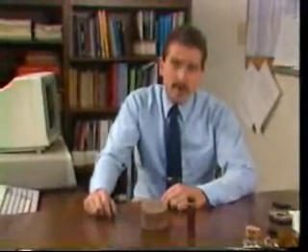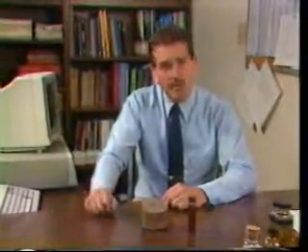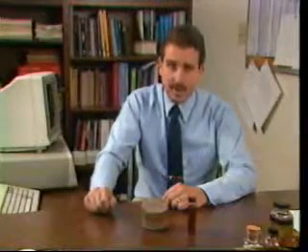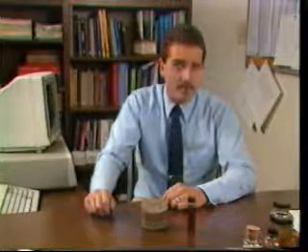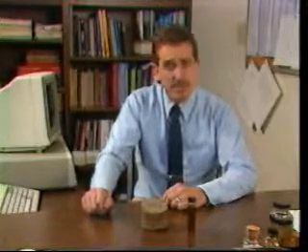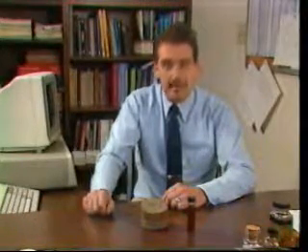Let's summarize the material covered so far. In the first unit, we mentioned the basis for well test analysis and interpretation. We spoke of three necessary equations: a continuity equation, a transport equation, and an equation of state to derive the diffusivity equation, the basis of pressure transient analysis. We spoke also about the two methods, the conventional and the modern, and the way that each approach treats the pressure in time data. Lastly, we spoke of the derivative curve and its usefulness in providing interpretive information beyond what is available from a typical log-log plot of the data.